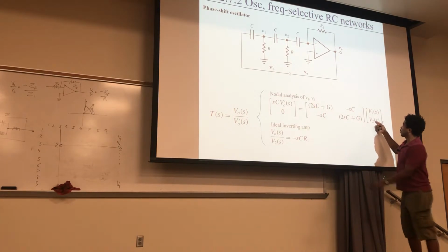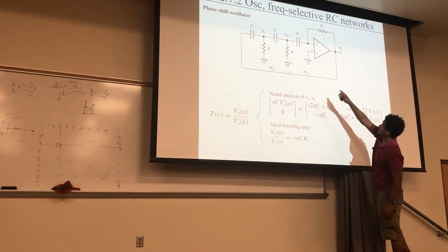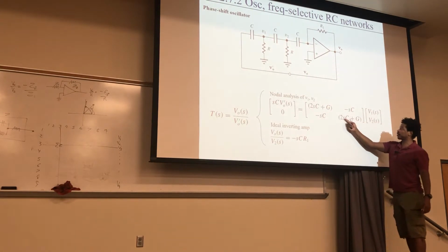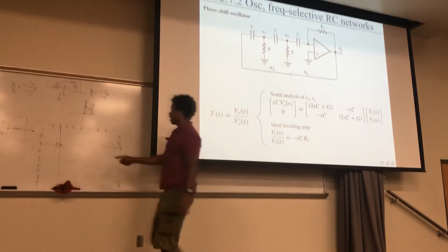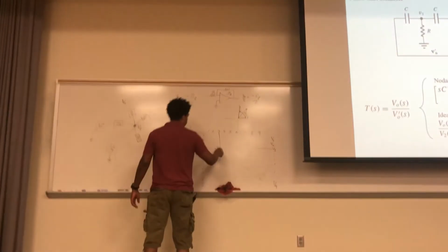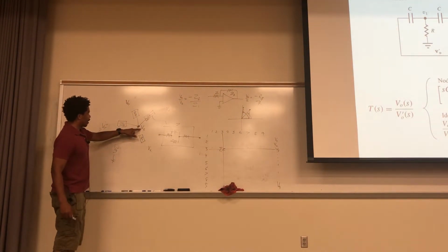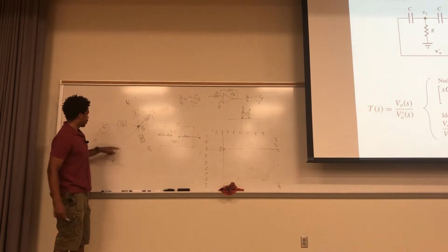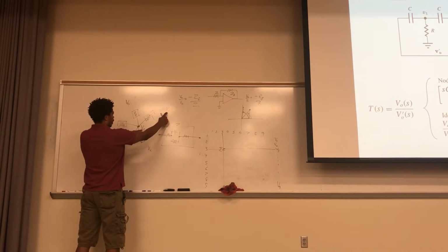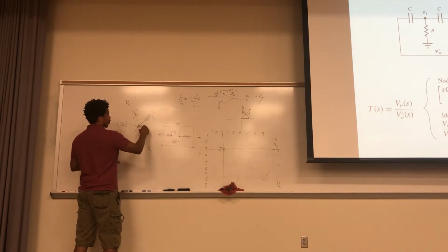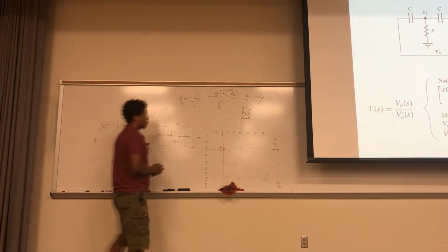And for V2, which is where those 2 things meet, you also have 2 capacitors and a resistor. But you have more. So you sum them all up at that row and that column. Now, that's V3. Now you have some cross terms, right? So at V3 and V1, at that cross term, 1 and 3, you're going to put a negative Z4.